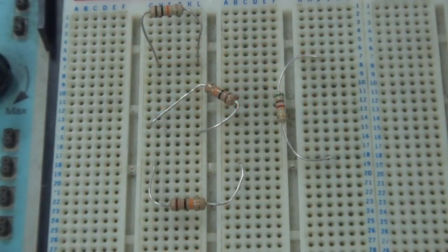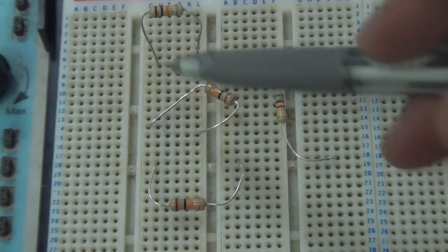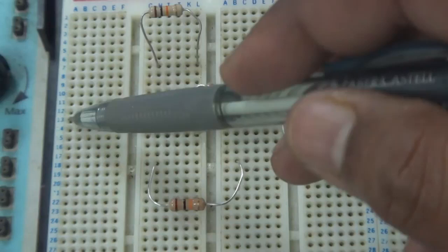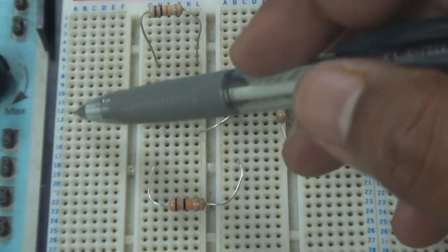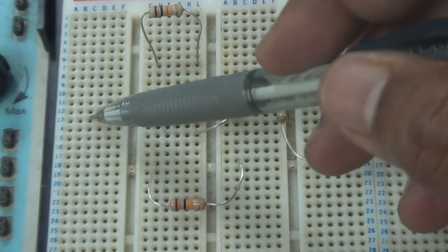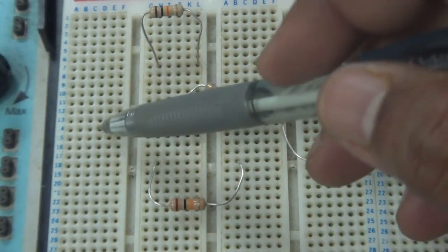When placing components onto the breadboard, you need to note how the connection is on the rows of the breadboard. So each row here, you have 5 ports that you can use to connect, and all these are actually connected to one another.